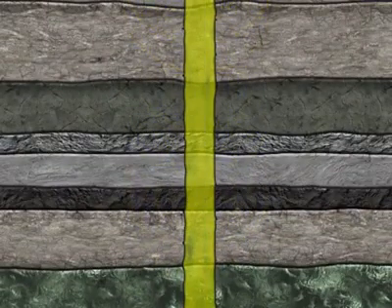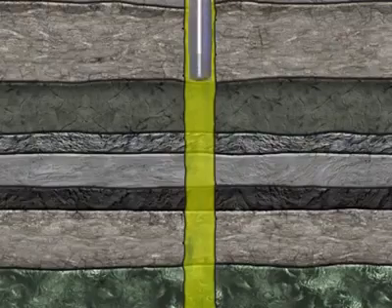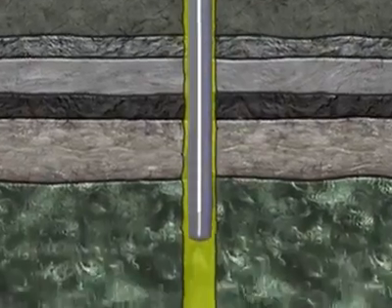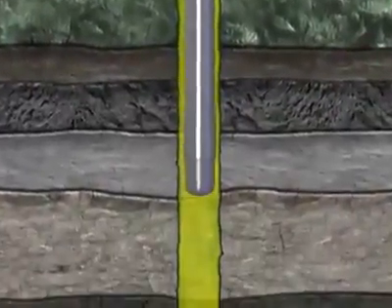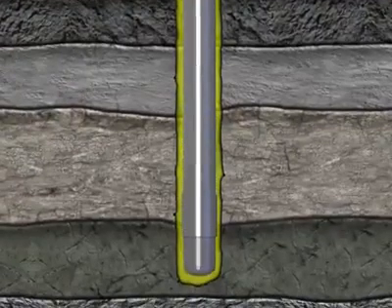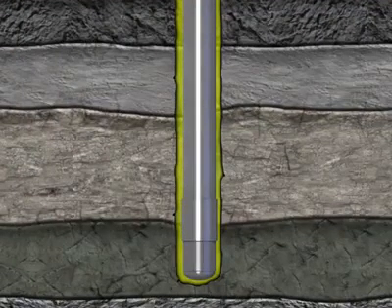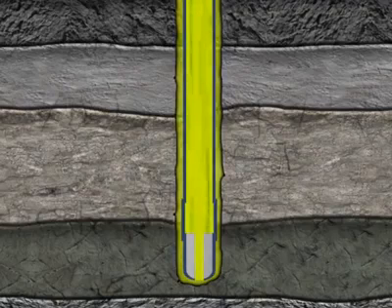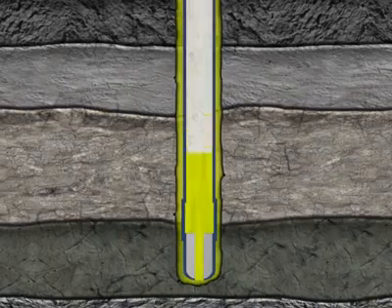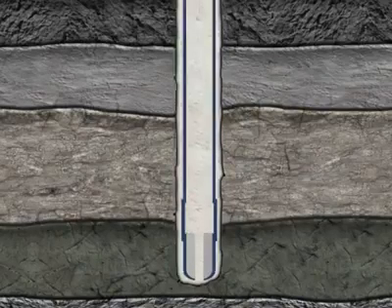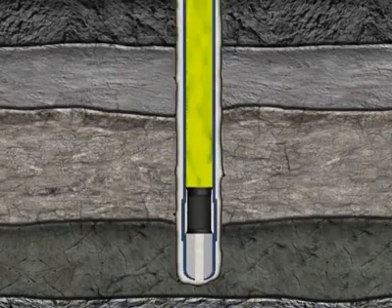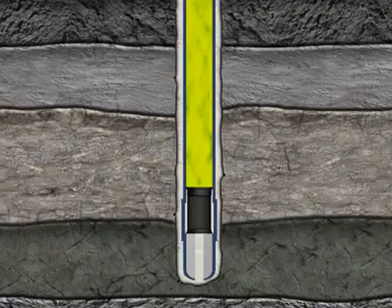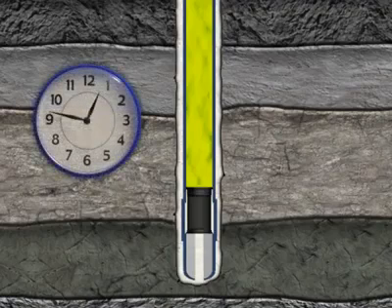After the pay zone has been determined and deemed feasible, the well needs to be prepared to extract the discovered hydrocarbons. This process is known as the completion of a well. A common completion method requires inserting a casing string into the newly drilled open hole to prevent the borehole wall from caving prematurely during the various steps of completion. To allow further operations in the well, the cement requires sufficient curing time.